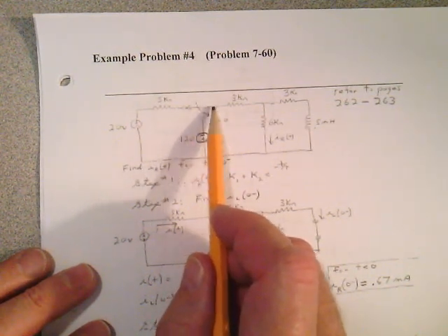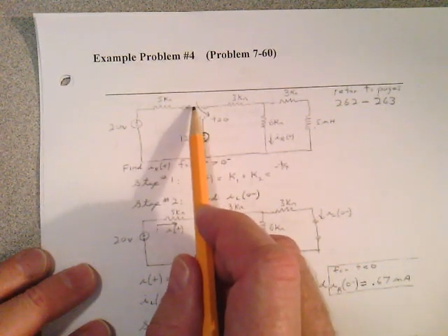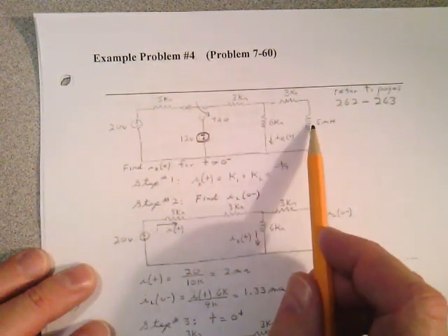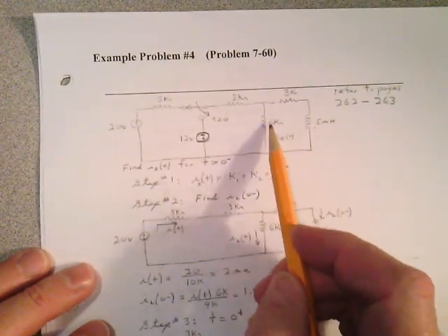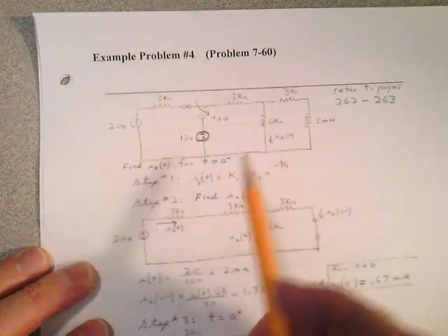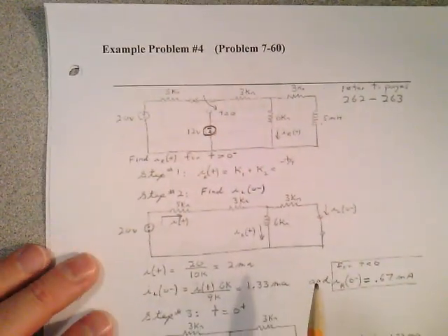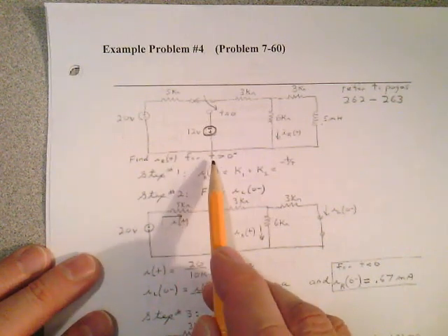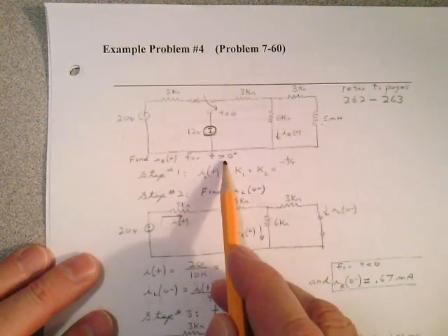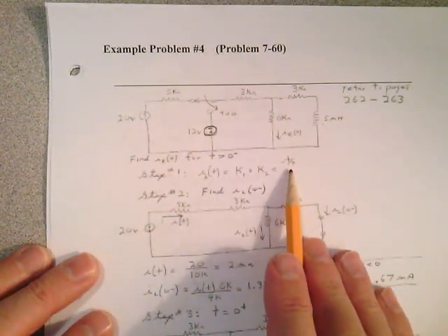That's going to get you through step 2 to 3. That sets up an initial condition with the current over here, but more importantly with the current here, because that's what we're looking for. And at t equals 0, you open that switch. So I want you to find I sub R at t, for t greater than 0. Step number 1, there it is.